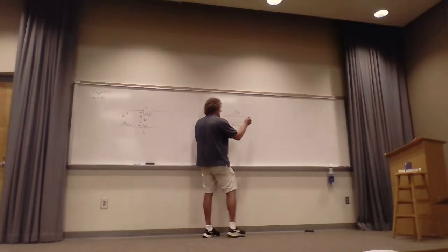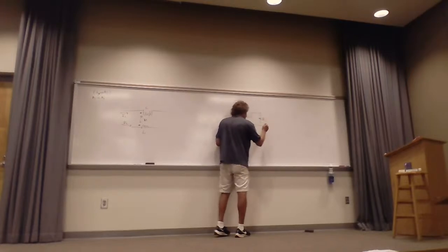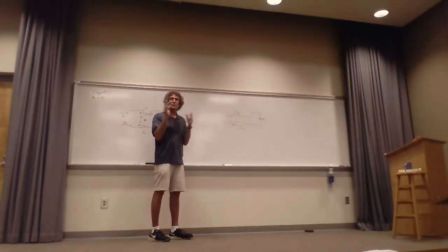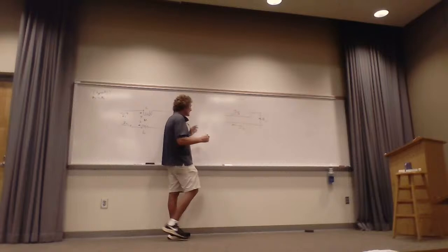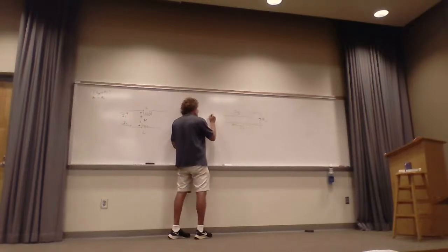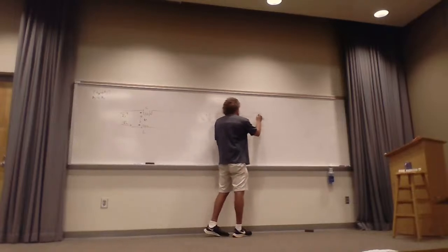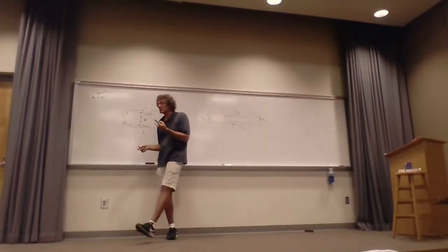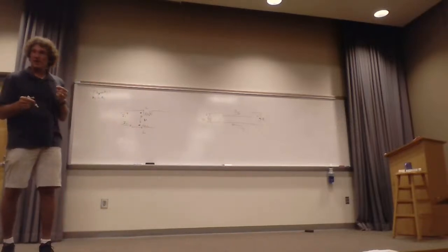Let me just show you the badness right here so you can appreciate it. If we think about this as a standard thing, let's make it real simple. Let's put this resistor over here, R load, and that represents some input to a device. It could be an FET input without the capacitor. It could be very large. Now we have a signal, and this is V of the source, and everything is fine. If I got a source here, it's felt across here, and the current through RL is just the source voltage divided by RL.